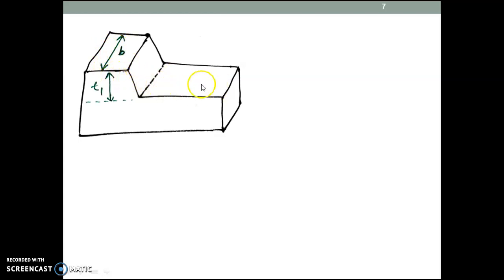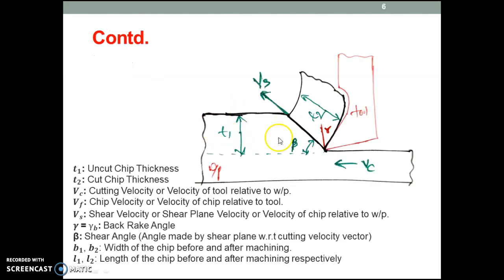If the volume is decreased in the length direction, then that volume has to be increased in either the thickness or width direction. As the thickness direction is weak compared to the width, the volume decreased by the tool will be increased along the thickness direction.